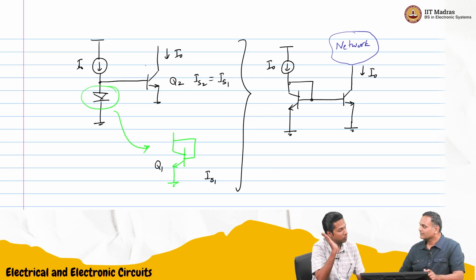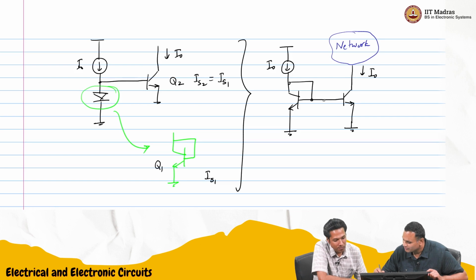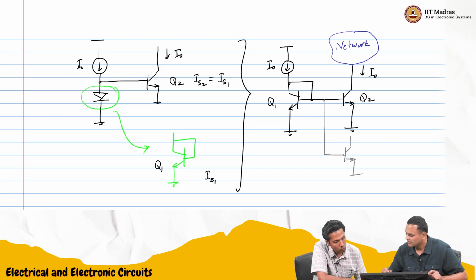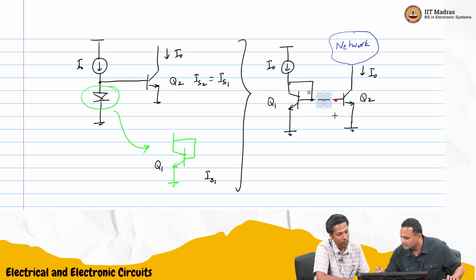So if I have one more amplifier, I can mirror once again. Yes, indeed we can. So we can create one more mirror by taking the same base emitter voltage and connecting it to the second one. So let us say this was Q1, Q2. For that we will draw separately. So right now we'll just show this. So this is your current mirror, that we have promised.